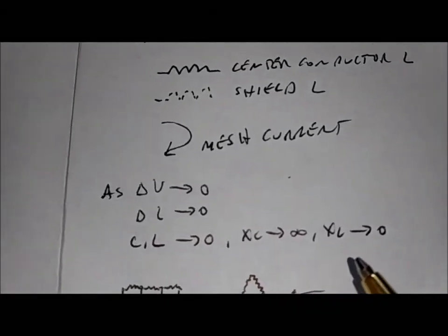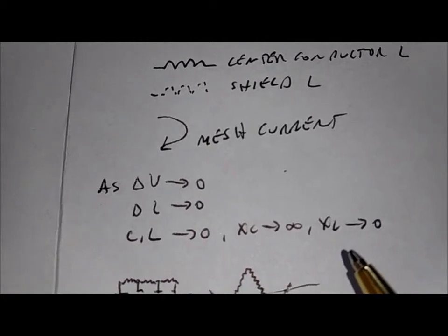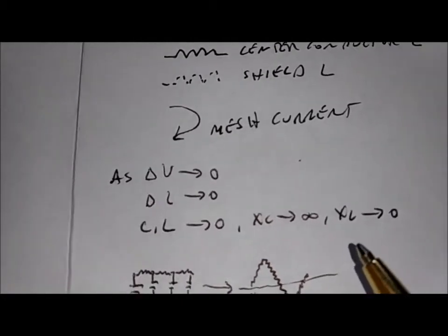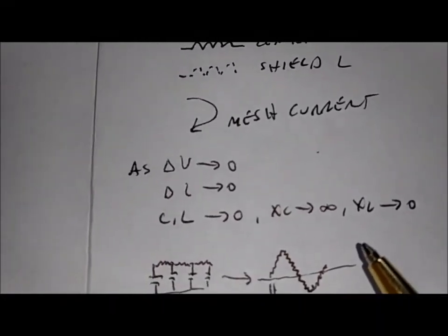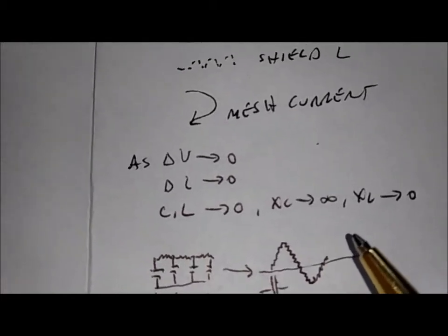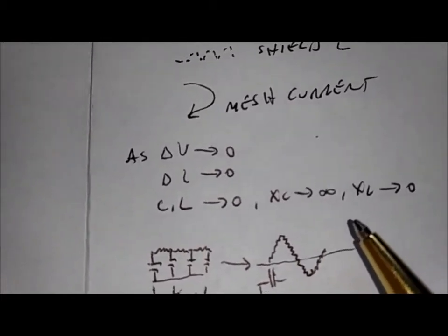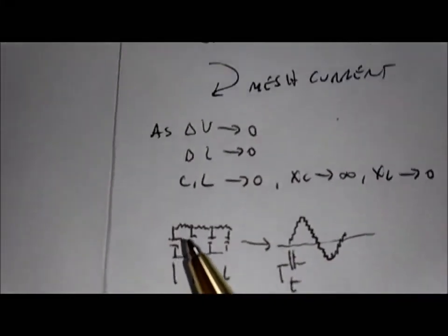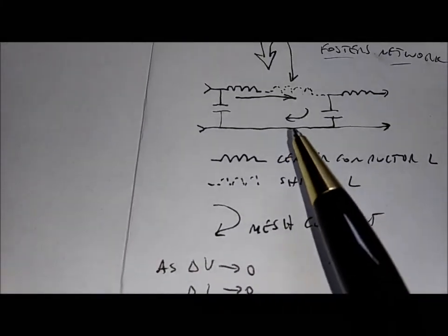Well, doesn't that become basically a short circuit? Yes, it does, except for the sum effect of dielectric losses. The energy is propagating through a dielectric. There's going to be some losses, and we know what transmission line losses are. But schematically, instead of this large mesh,